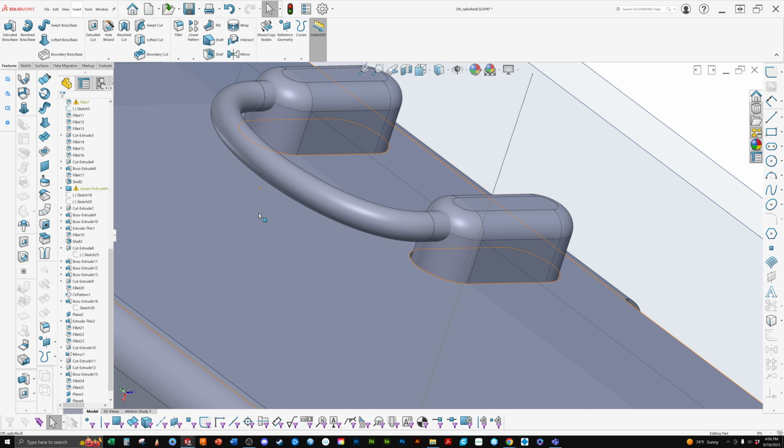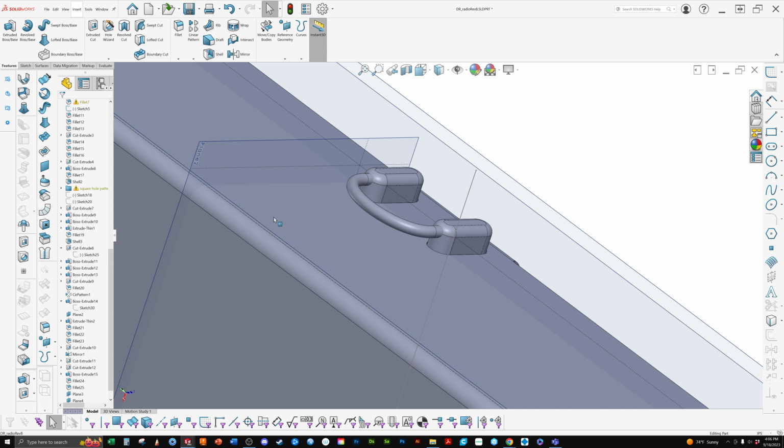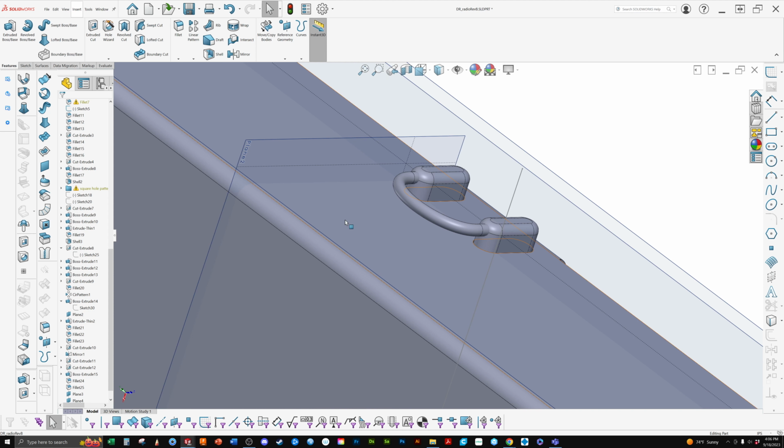Normally, it's good to have everything moved together so that the circle is connected to the path. And the reason for that is that way you just know where things are and you don't have just sketches that are floating around. So what we did was two things. We created the sketch, the path first, and then we created the sketch. And we said for the circle that the circle is connected to that center of that sketch.